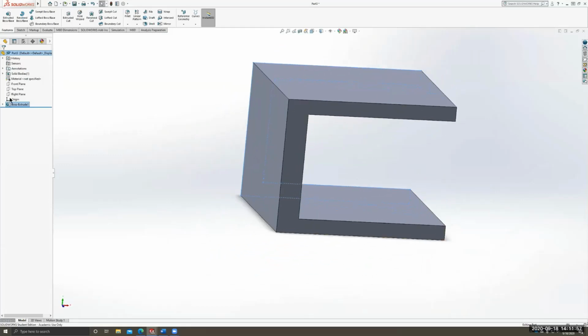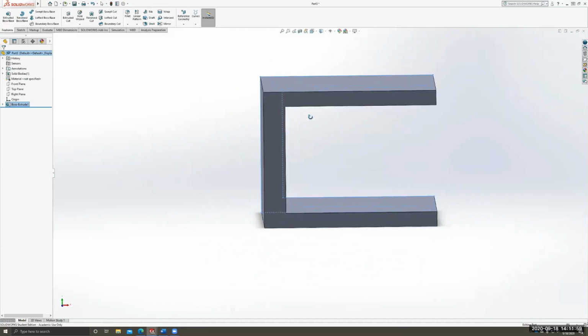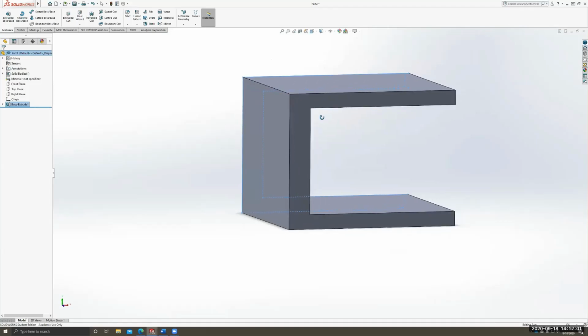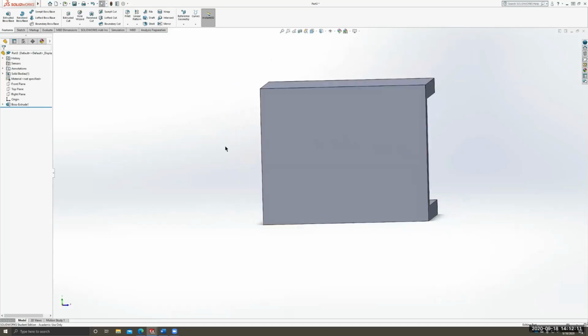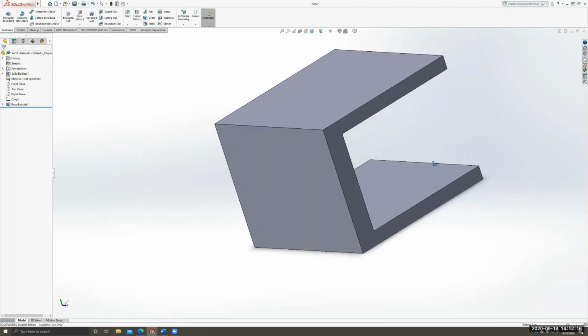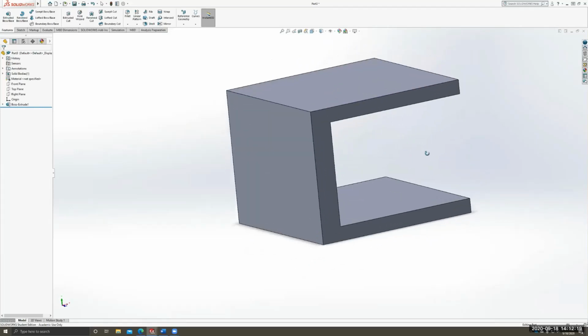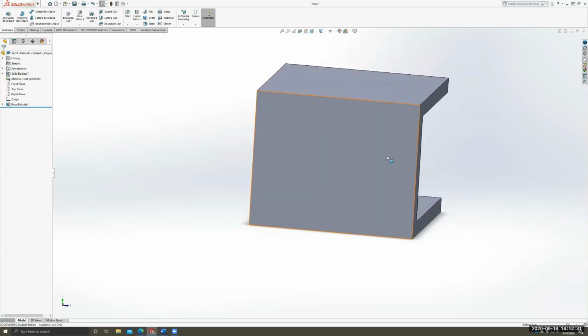Now we're going to make the tail. So there's, again, two ways you can do it. You can either draw your sketch on this face and have it go all the way out and extrude it back. Or we can draw on this face and then have it extrude out again. Do you guys want to see both or do you want to just see one? No preference? How about start on the back face? This one right here? Yeah. Okay, let's do that.